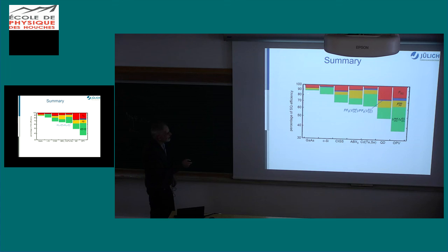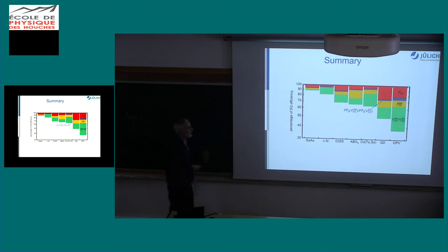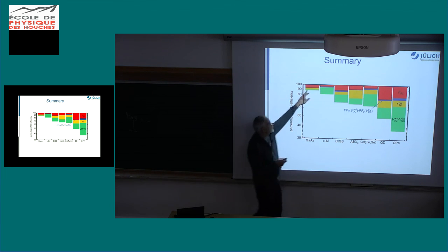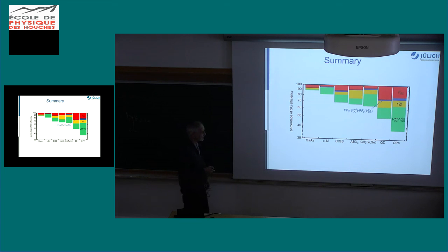But you see, then everything here, there's almost no loss between the VOC and the VOC Shockley-Queisser. So that's really at the radiative limit and has at the same time a very steep, sharp band edge. And also almost no resistive losses here.